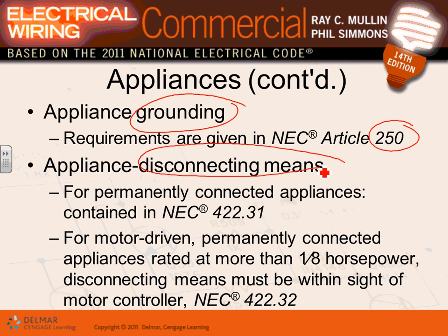It's not just electrically speaking, guys. All these machines do so many functions, think about it. Every single manufacturing plant has tons of machines that have to be cleaned, worked on, maintained, troubleshot, and what not. So when you lock this machine, you de-energize it, you lock it, you tag it with your own lock. Nobody else other than you can energize this equipment. So your chances of surviving are much, much higher. Okay, so that's your disconnect. Everybody knows what a disconnect is.